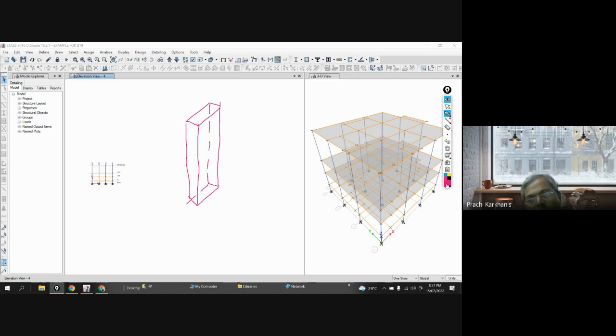For the column, I will have always I at bottom and J at top by default. And you're drawing a column by just clicking a point. That's why he will consider I at bottom and J at top, and you will see this is your one axis.